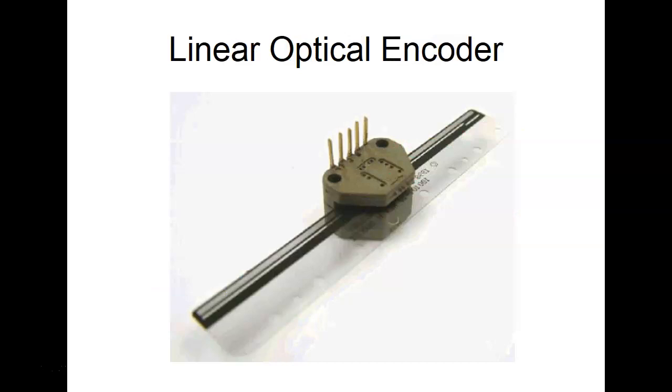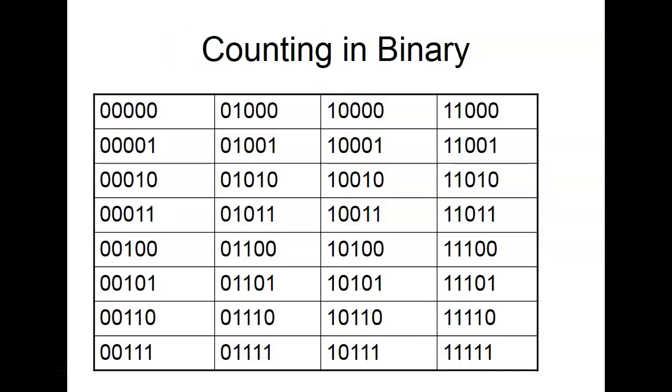So what we primarily use is counting in binary. So counting in binary, right? Y'all see how this goes? Now, the problem when we count in binary is that we have a term called propagation delay. What happens is the more counts that change, the longer it takes to go through our counters, which are actually doing the counting for us.